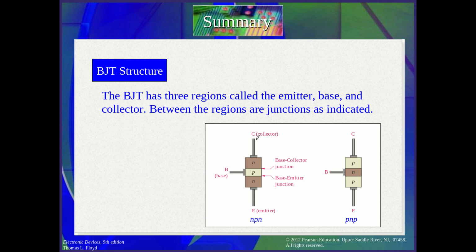Okay, so what I am speaking about today is something called the bipolar junction transistor, which is formed by 2 PN junctions, either PNP or NPN. It consists of an emitter, that is the most heavily doped of the 3 regions, and a base, which is thin and lightly doped compared to the other regions, and the largest region of all of them, but moderately doped, the semiconductor region. This we call the collector.